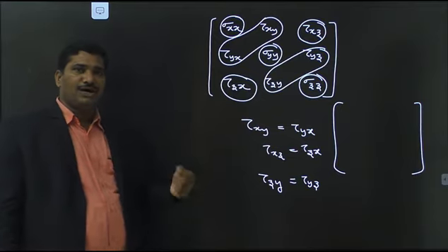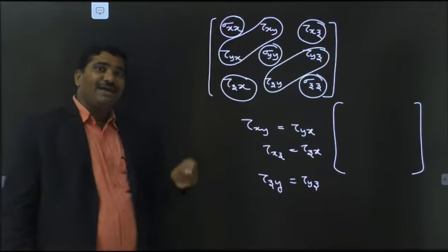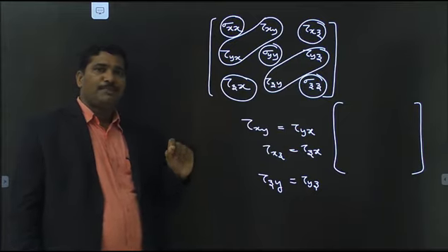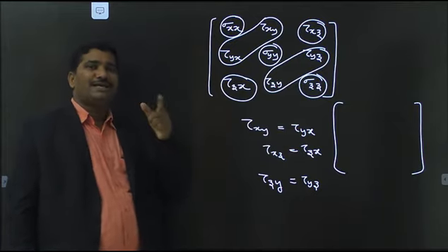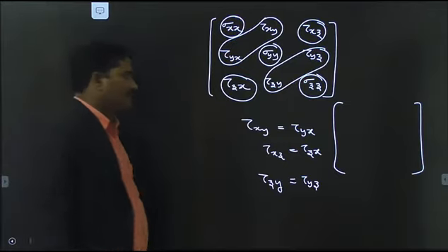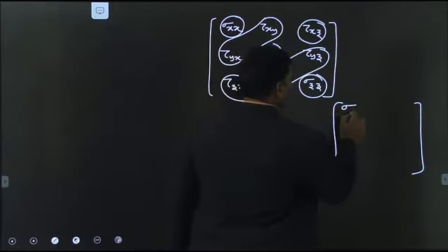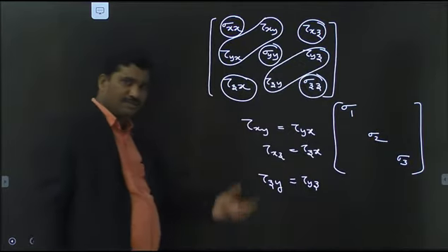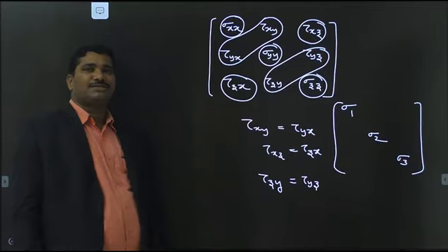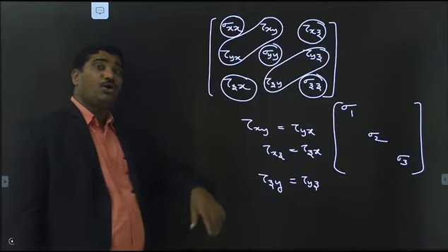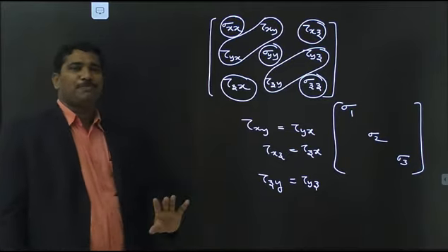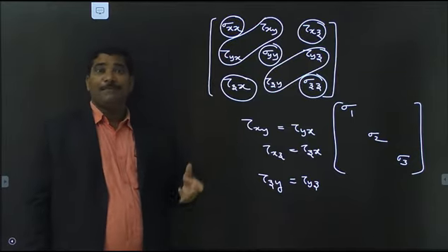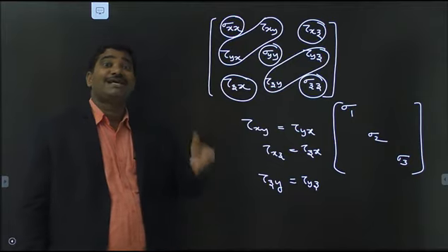This is the reason why, for a 3-dimensional state of stress with principal stresses acting in their principal directions, you can write the matrix with sigma 1, sigma 2 and sigma 3 on the diagonal. Principal stresses are only normal because the principal plane does not carry any shear stress. You can say the principal plane is the shearless plane.